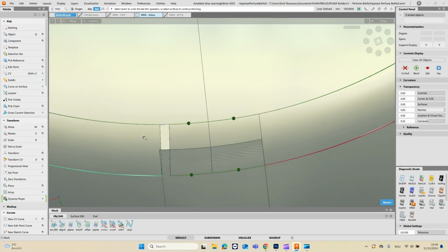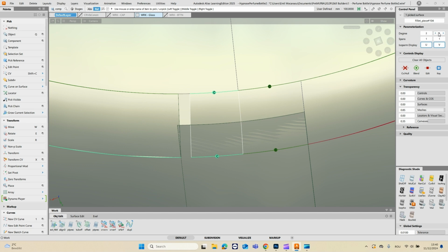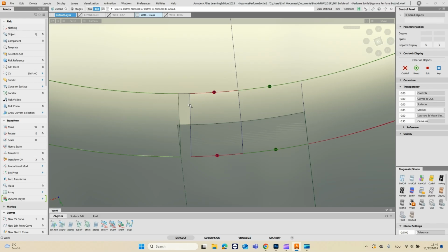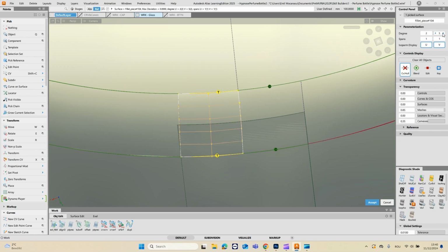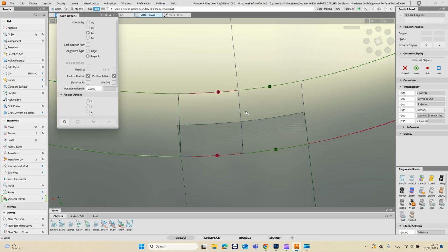And we have this little gap here. So what we will be doing is taking that surface, I'll take it down to degree 2, extending it there, then this surface becomes degree 5 again, and we align it curvature first to those 2 edges and then those 2 there.